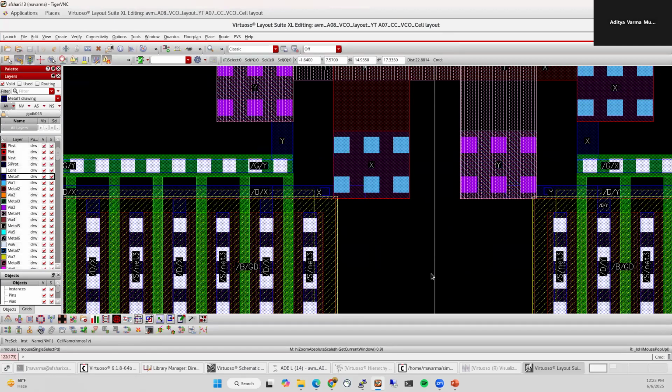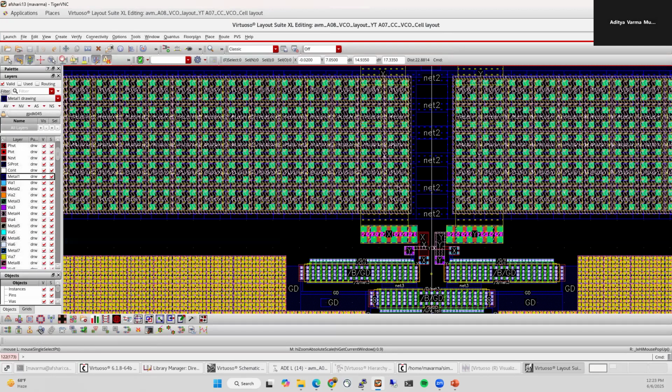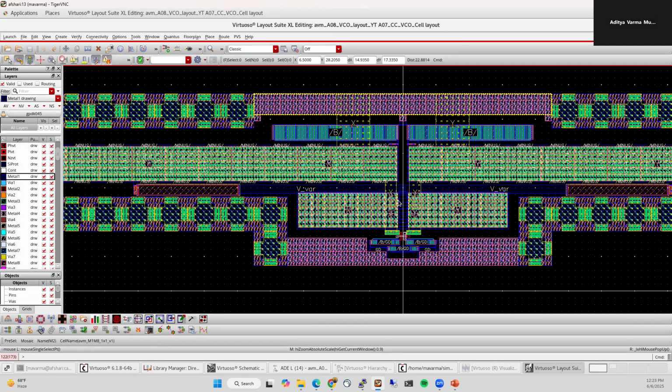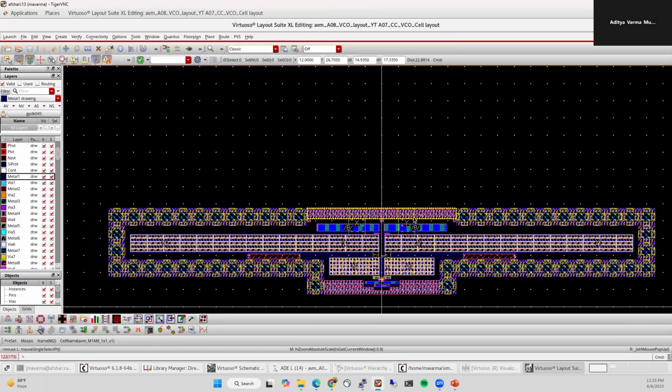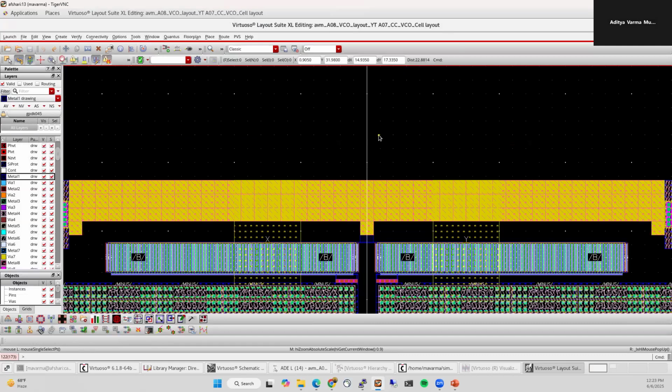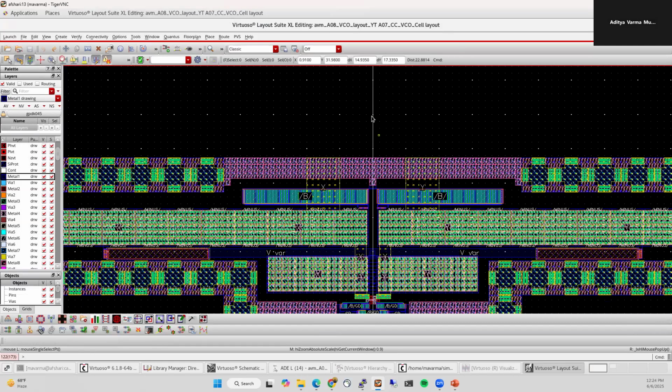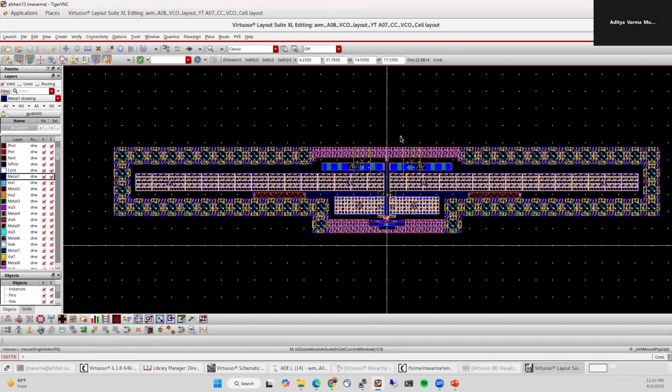You need to place the pins correctly even in Cadence out here, and we'll see that it can have an impact as well. So we'll correct the pin locations. We'll also remove that parasitic inductance that comes from the lumped ports in HFSS. And we really need to discuss how to properly transition from HFSS to Cadence in this kind of co-design environment. That's the next thing we'll discuss, maybe not in the next video, but in future videos.